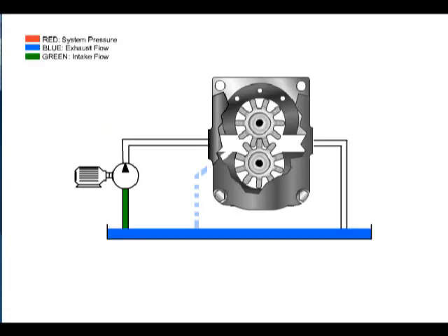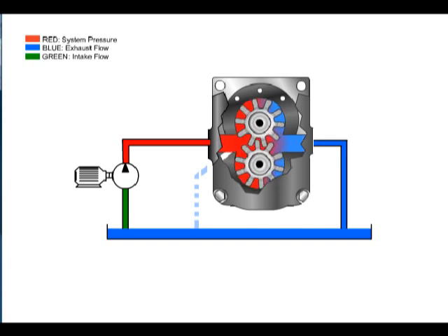Hydraulic motors are classified as rotary actuators. Motors very closely resemble pumps in construction. However, instead of pushing on the fluid as the pump does, the fluid pushes on the internal surface area of the motor, developing torque. Resistance from the load is encountered, and pump flow provides a continuous rotating motion. Since both inlet and outlet ports may be pressurized, most hydraulic motors are externally drained.